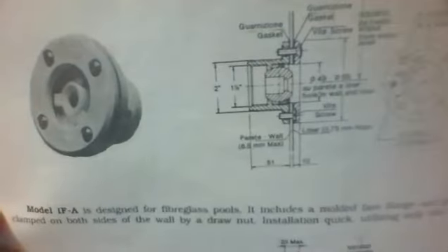Fittings have an outlet that is threaded 1.5 inches female and 2 inches male for optional pipe sizes. Another model is designed for concrete pools. It includes a no-leak flange with two mounting holes and a protection cap over the face. Here different sections are shown, and you can see these sections. There's one section here, model IFL, then a different one, model IFA, and then this other one.